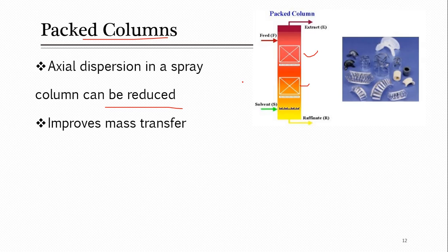You already know that if there is only an empty vessel and two liquids are coming in contact with each other, they don't give very good mass transfer. But when we introduce some other structure like packing, you know that packings are introduced to improve the contact time and mass transfer. So with the help of this, definitely mass transfer improves. When mass transfer improves, the extraction of the component which we were supposed to remove from the feed will improve. That will become more a part of the solvent.